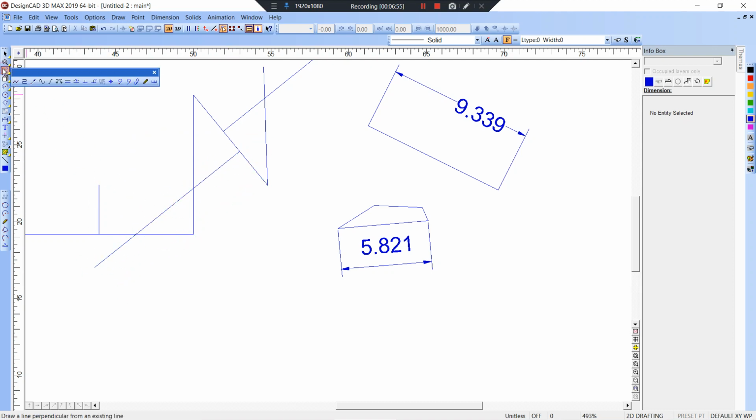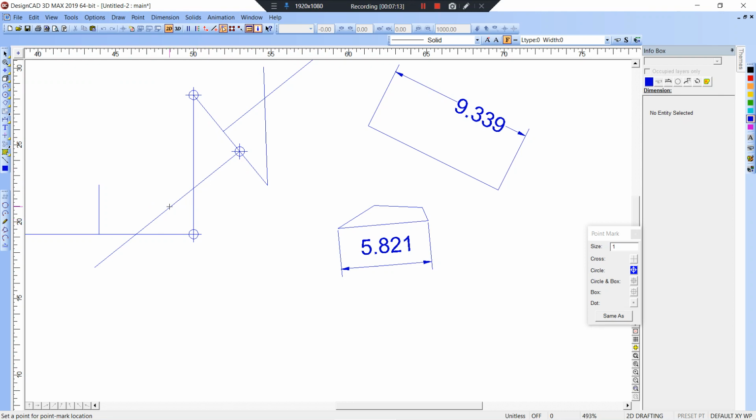The next one would be, I don't even know what that is. I'm not sure. Maybe it's 3D only. There's your point. Insert a point. If you hit Control K, it goes to the middle of the line. Your endpoint is a right click, and then K is the nearest to the line, it snaps to the nearest entity. So if it was a circle, we just go to the nearest spot.